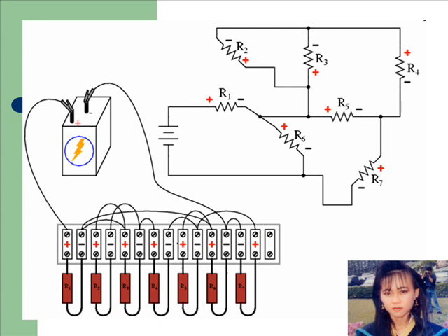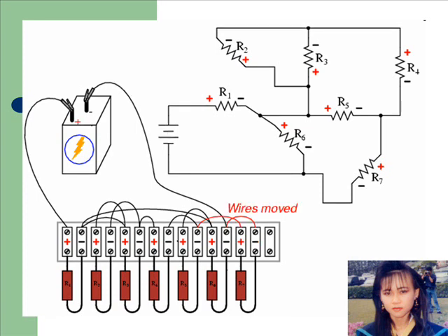Would the circuit have worked this way? Certainly, it's just that more than 2 wires secured at a single terminal makes for a messy connection, one that is aesthetically unpleasing and may place undue stress on the screw terminal. While this poses no electrical problem,